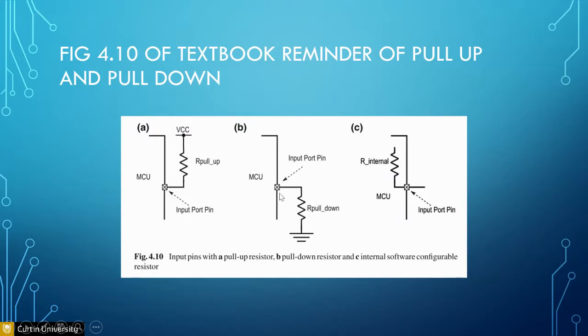but in the pull down configuration, this one will normally be 0 volt. So you might decide that if nothing is applied to the signal, it is a pull down configuration. But the thing with embedded systems is you can have an auto configuration. Still remember PXREN that I asked you to investigate yourself? You give a value to PXREN, and it will internally set it as pull up or pull down. Again, I repeat, if you don't want to do it using a circuit, this is a pull up configuration. Pull down configuration in your embedded system is configurable using the PXREN register.